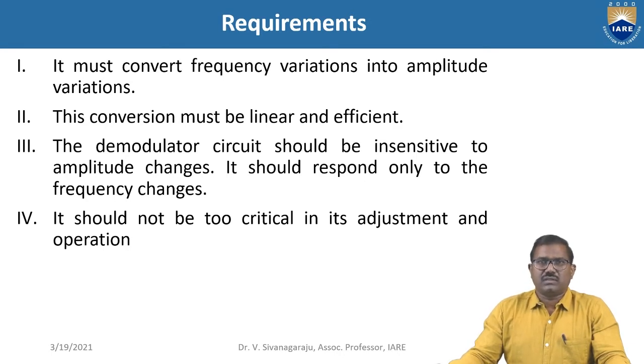And the third one, the demodulator circuit should be insensitive to amplitude changes. It should respond only to the frequency changes. And the last one is it should not be too critical in its adjustment and operation. That means the operation is simple. So these are the requirements that must be fulfilled by the demodulator.